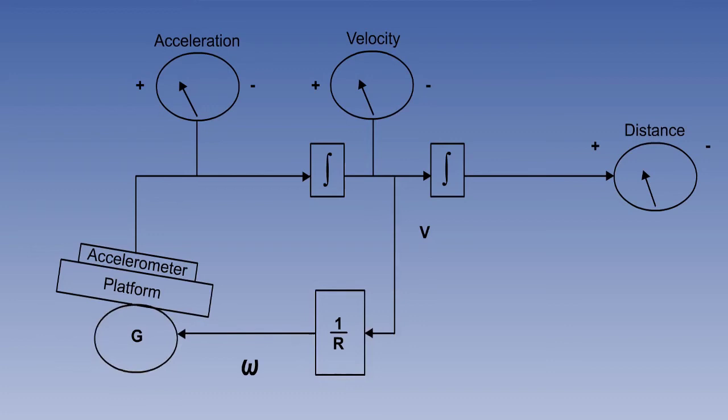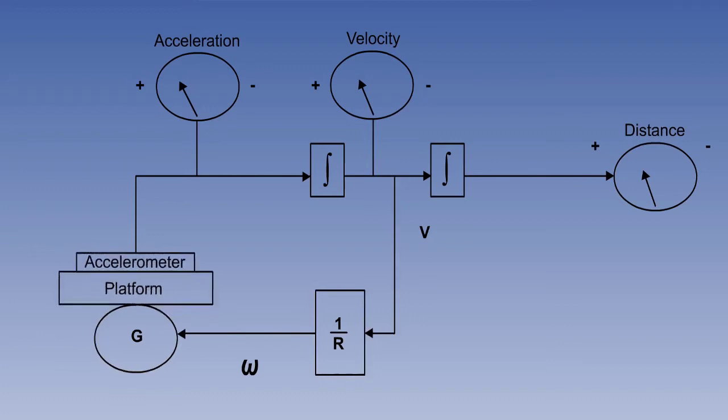The system can't tell that we are still on chocks, and this is a false velocity, so it assumes that the aircraft is travelling around the curvature of the Earth, and slowly brings the platform to the level, which means that the source of the false acceleration is removed. You might think that this has solved the problem. The platform is now level, and there is no false acceleration. However, it hasn't. We have a build-up of velocity.